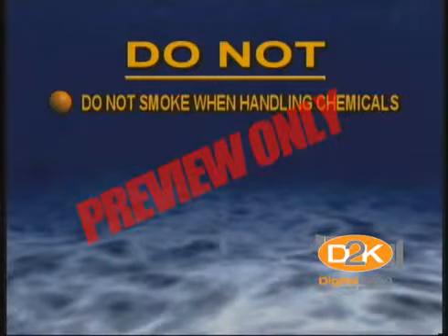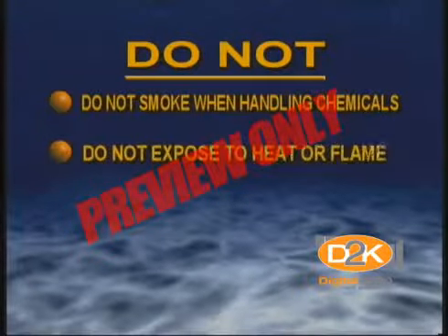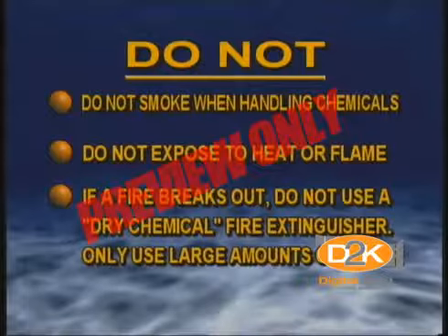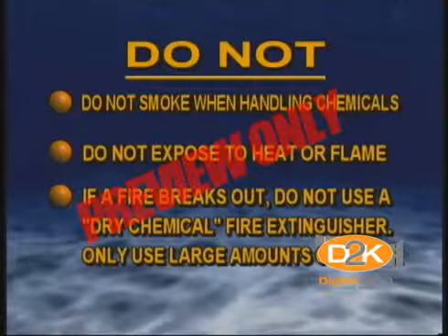Do not smoke when handling chemicals. Do not expose to heat or flame. If a fire breaks out, do not use a dry chemical fire extinguisher. Only use large amounts of water. If you cannot extinguish the flame immediately, leave the area and call the fire department.